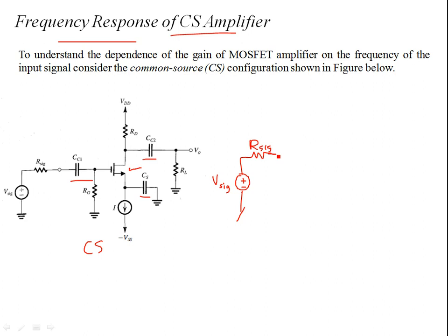But just to concretize our understanding with previous circuits, let's first of all neglect those capacitances in the small signal model, just to drive the circuit without the capacitances and find the mid-band gain. That is the gain without frequency dependence. So we have R signal, then we have RG, the biasing resistance at the gate of the MOSFET. So this is the gate terminal.